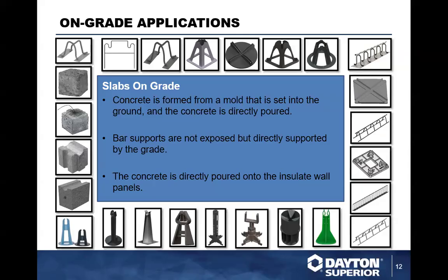They will suck the moisture out of concrete and give you shrinkage cracks if you use them on something that's going to be exposed. So as long as it's going to be sitting on the ground, wet them well, basically soak them right before you pour your concrete, and go to town with it. They are a great option. They're a 4,000 psi material, so they're good and strong.